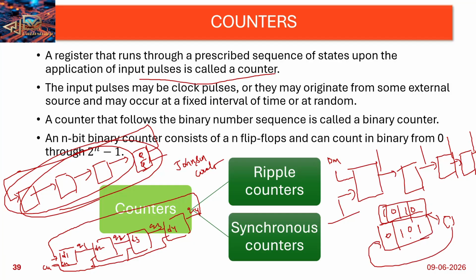Okay, so for an n-bit counter, see how many clock cycles are required to place all the data. Four clock cycles are required. That means for an n-bit ring counter, n clock cycles are required, but for a Johnson counter, 2n cycles are required.